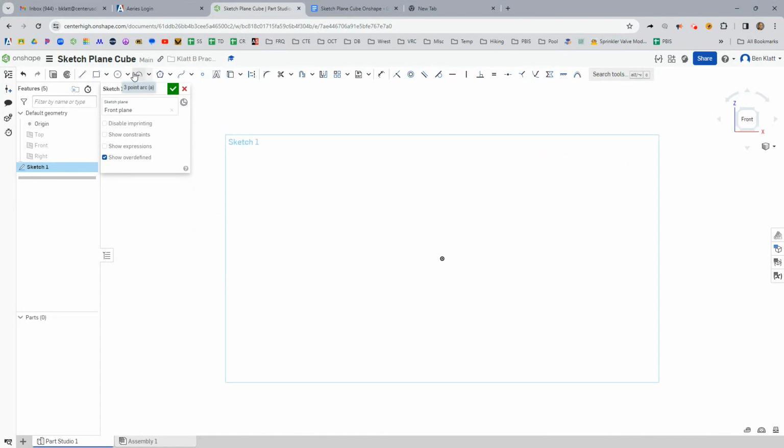All right. Let's go ahead and start by doing a corner-to-corner rectangle. This toolbar up here, you may not see the same things depending on the size of your screen. You might have to use drop-down menus. And we'll hook up to that origin point. Now, just like Fusion, when you have an undefined object, it's going to be blue. Now, let's click out here. You can always undo, and notice that it's going to give us one option for one of the sides.